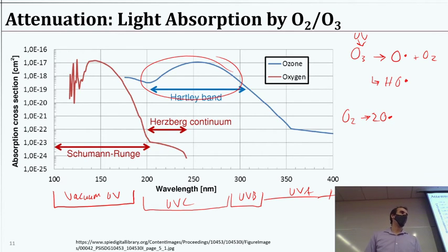So when I've been hearing for the past year all these discussions about ultraviolet light for coronavirus, let's put it indoors, let's put it in our HVAC systems, I'm thinking to myself, are we taking care that we're not adding a bunch of ozone? That's a lung irritant. We ought to consider, if we are using these new 222 wavelength lamps, that's going to create a lot more ozone than a 254 lamp. So let's at least be mindful of that and consider it as we're designing our UV controls.